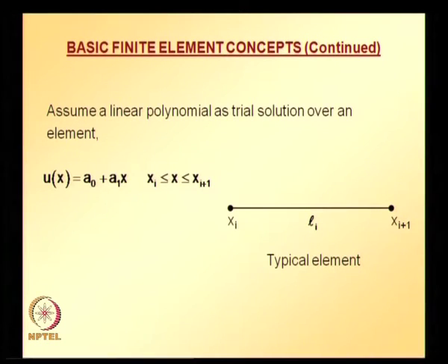One of the basic concepts in finite element formulation is that the trial solution is expressed in terms of the unknown solution at the nodes. So, we are going to replace a naught and a1 with the unknown solution at the nodes. These unknown nodal values act as parameters to be determined by various techniques that you already know, that is variational or weighted residual methods.